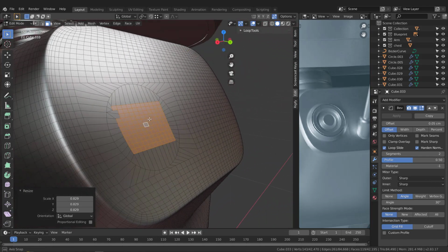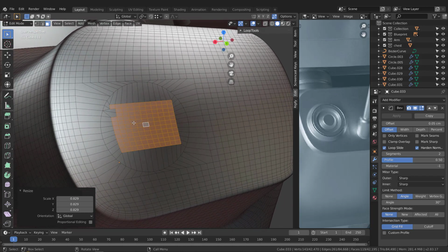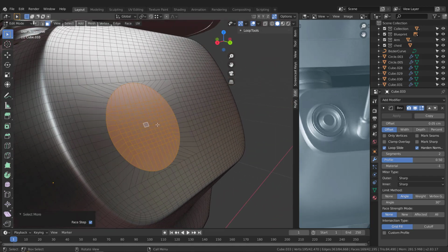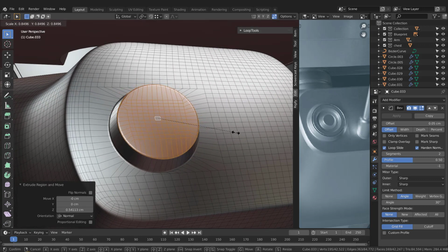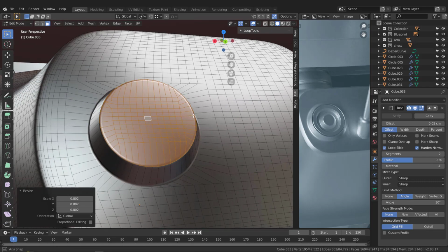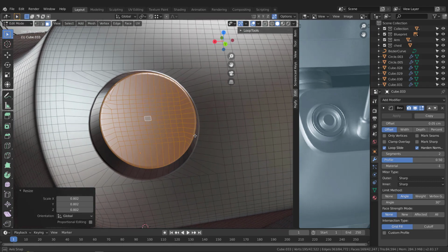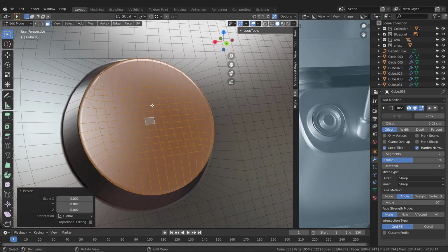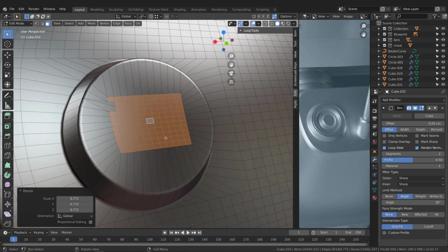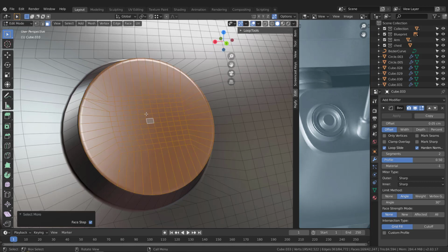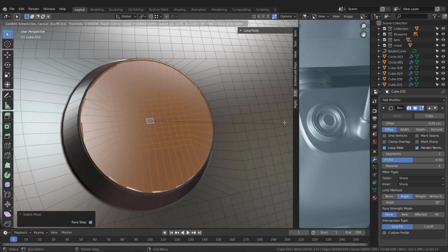Now this will work. Well, after that, now what we can do is Control plus to grow the selection, and we can hit E to extrude, and we can extrude this almost right here. Let's see, where should we extrude this, and scale it just like that. And maybe I can insert this result, but let's hit Control minus to shrink the selection, and I will scale this more, and then grow the selection again, Control plus, and then just hit I to make an insert, just like that,